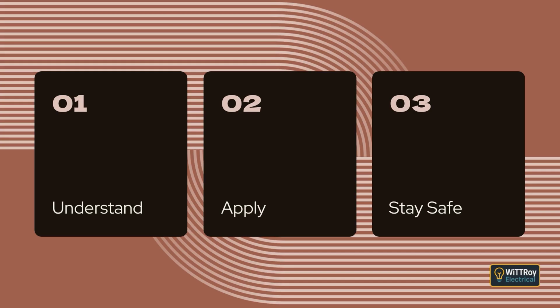A switchboard must not be placed near baths or showers because of moisture and condensation risks. The same rule applies near saunas, swimming pools, or spa areas, as explained in Clause 6.3. A switchboard must not be installed inside a refrigeration room.